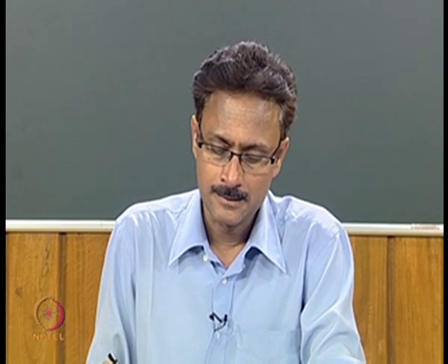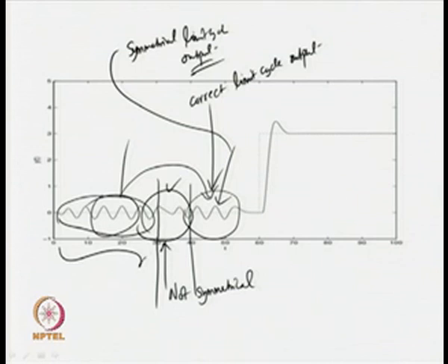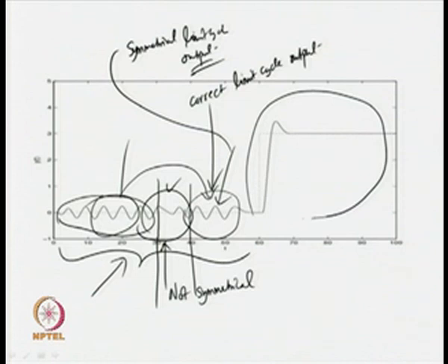Then when the tuning phase or auto tuning test phase is over, the relay is switched off. Then you get the normal operation of the system, and if you have tuned the controller properly, the controller provides proper dynamics of the closed loop system.